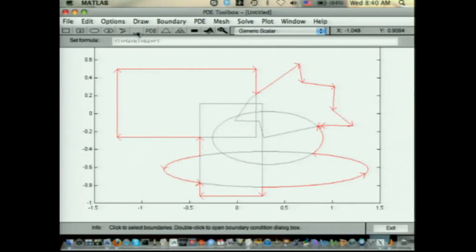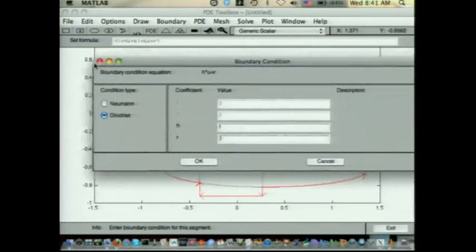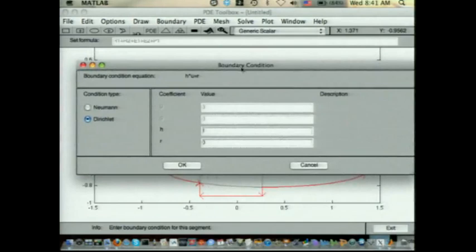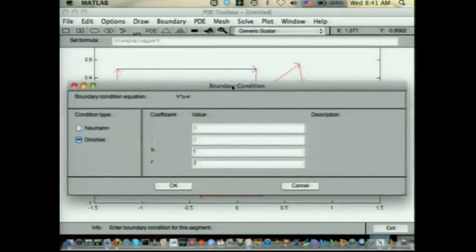Okay, so what it did is that I got overlapping regions, but really what I have is this region in red. And the red means something. So I can actually go here and let's say, let me go to this boundary line right here. See that one right there? Double click it. Oh, right here. Okay, and now it pops this box over here. I pull out from the corner. Boundary condition. Oh, look at that. For that line, I can specify a boundary condition.